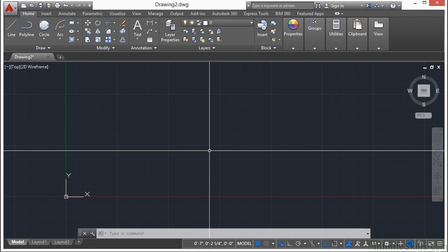Now, it's one thing to be able to draw lines and circles, but it's another to draw them accurately. O-snaps are one of the key features in AutoCAD that enable us to draw with precise and exact accuracy. O-snap is short for object snap. They force you to automatically draw from a specific point on an object.